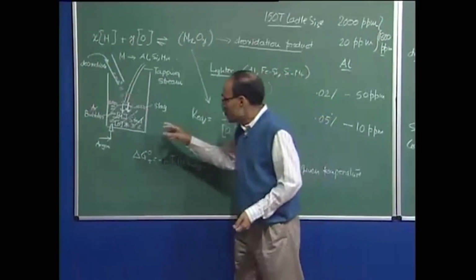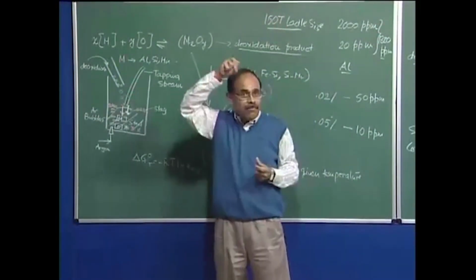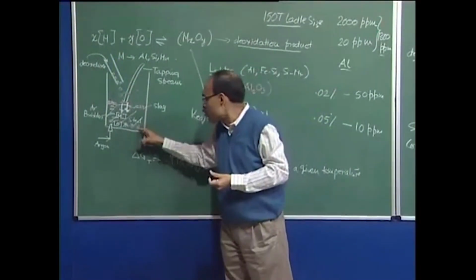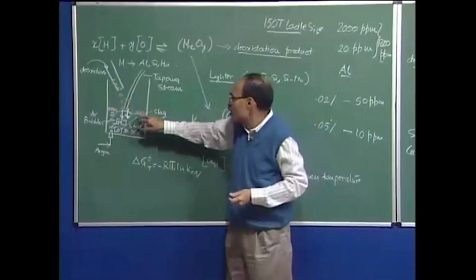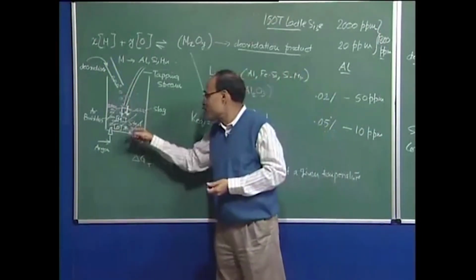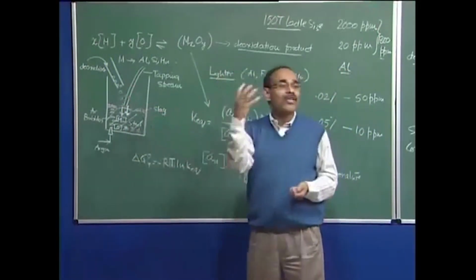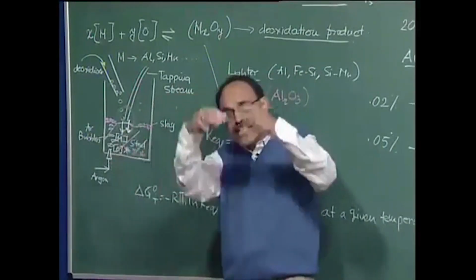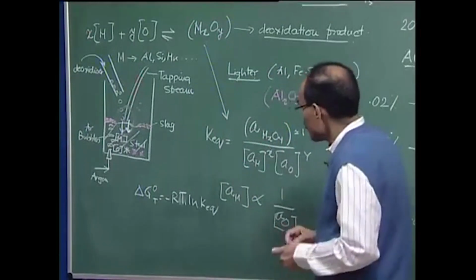Typically the deoxidation products rise to the slag metal interface, and the slag captures the inclusion. The slag removes these non-metallic or harmful inclusions, but the inclusions stay for some amount of time in the vicinity of the slag before they are completely captured by the slag itself. This is referred to in steel making reactors as the dwell time of the inclusions, or the dwell time of the deoxidation products. They have to dwell in the vicinity of the slag for some time before being completely captured by the slag layer itself.